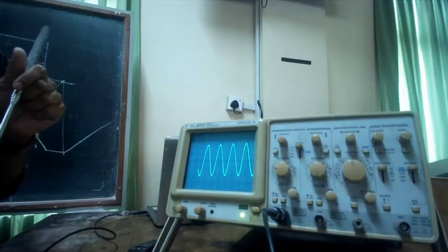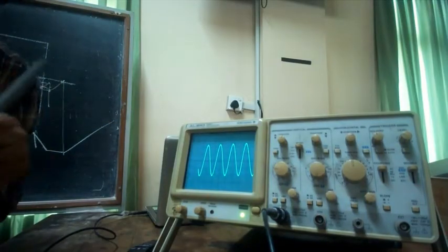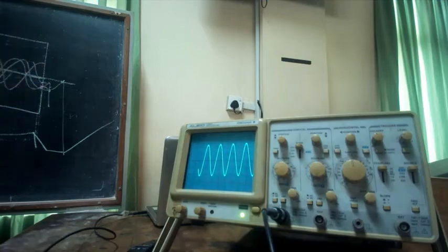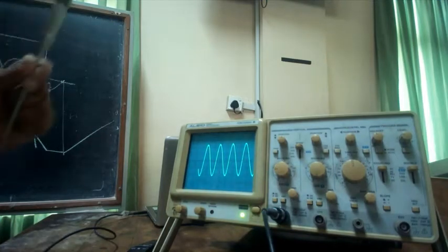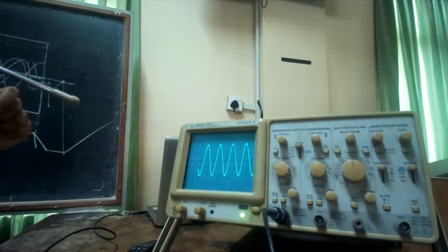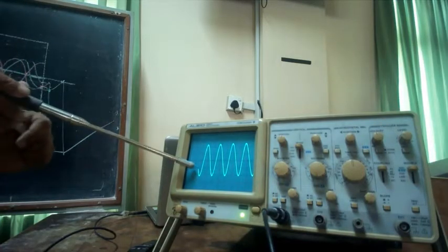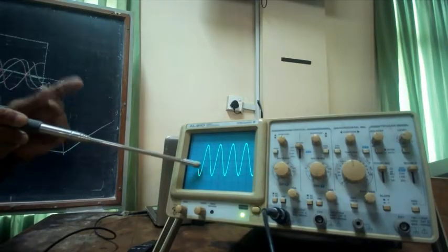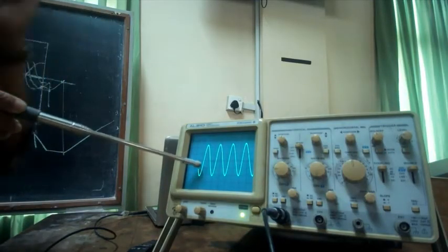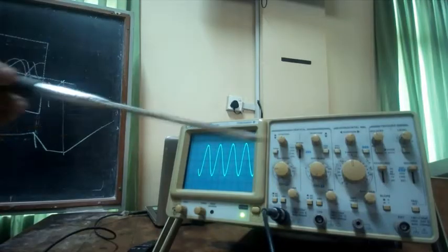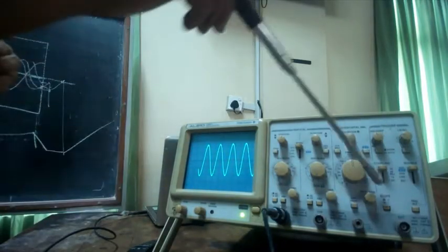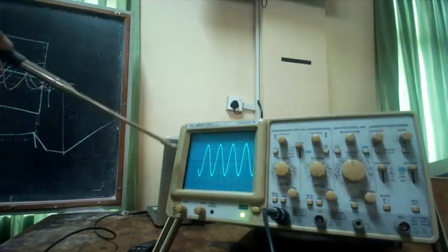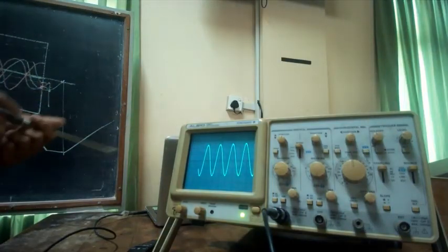It waits until that voltage is reached and the slope is negative. See, the slope is going down now. Yeah, it waits until it reaches that slope as well. Only if it reaches both, because otherwise at this point it also reaches that level, but it doesn't match the slope. I need this negative slope according to this setting, so it doesn't trigger. That's why it still waits.